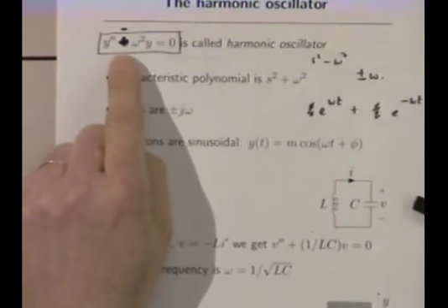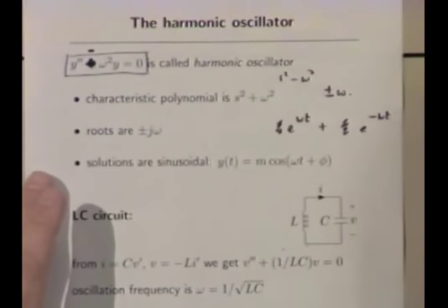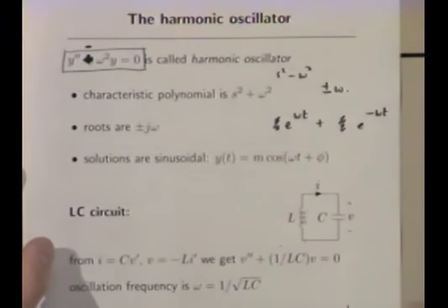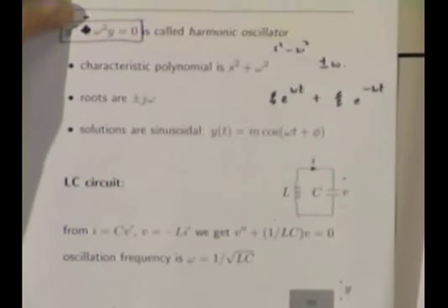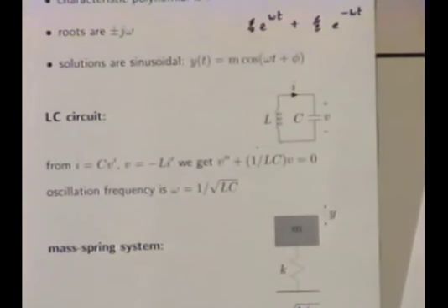But in an advanced fighter, when your nose pulls up, you catch more air, and in fact, it pushes you farther up. So there you get a term just like that. You might ask, why do they do that? And the answer is you get a snappier ride, much snappier. Because if you don't do anything, it just flips over, so there better be something there to fix this, which there is, which we'll talk about later in the class. So these are your two pictures of an oscillatory system.